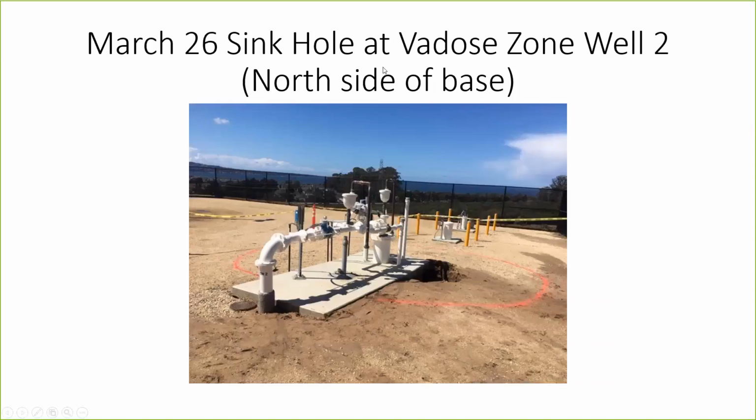We were able to get the geotechnical firm who did the geotech investigation for both Pure Water Monterey and ASR. They were able to come to site the next day, and they brought some equipment with them that allowed us to poke in and determine where the earth was firmer and where the earth was less firm. Working with the contractor, that pink, orangish circle you see is the area in which the soil was less firm than what we would like.